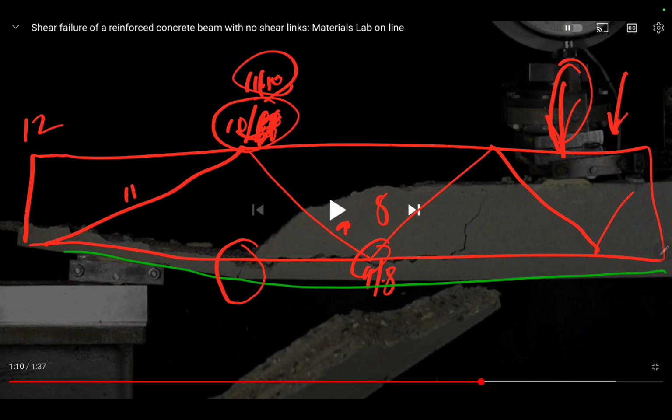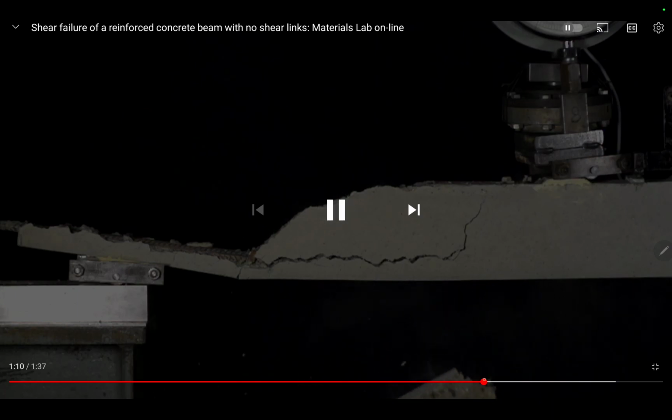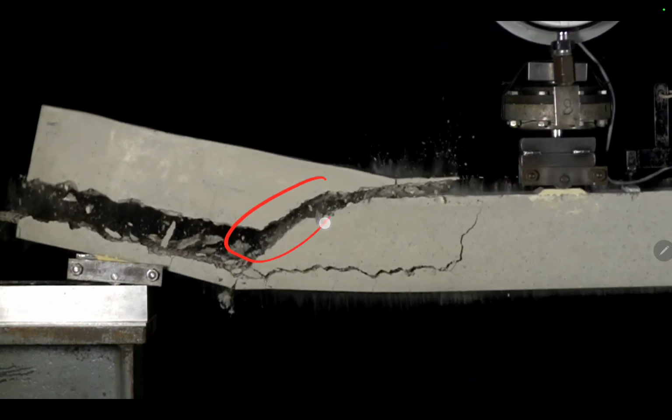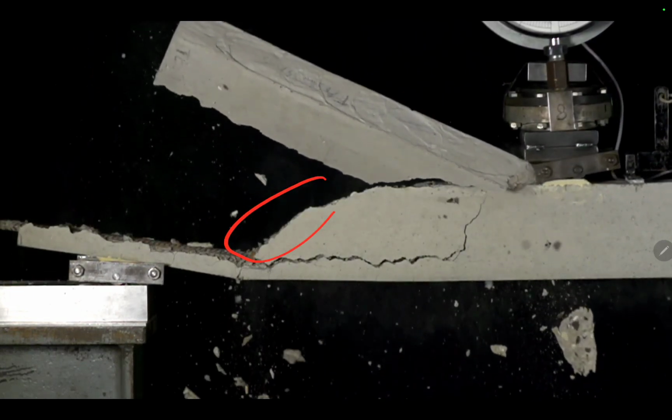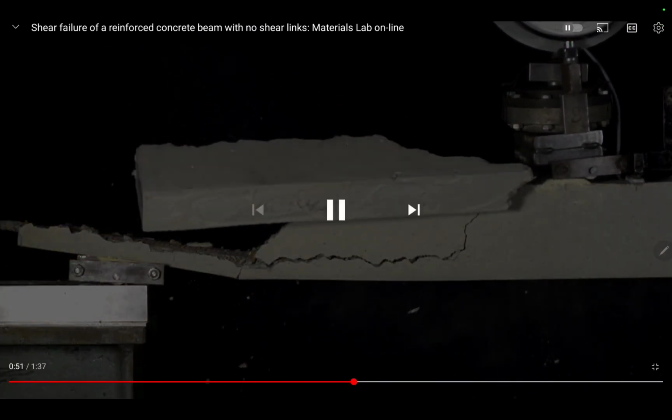This is where we get that collapse, where if you look at it, you'll find this collapse with the video camera of the FIU bridge collapse. You see the deflection here. Before we do that, let's go ahead and get this video going, and you'll see it break again. And here we go. If we slow down the footage, here is that failure again. Now remember, this is a beam in which we have left out the shear reinforcement, and this is the consequence. One more time.